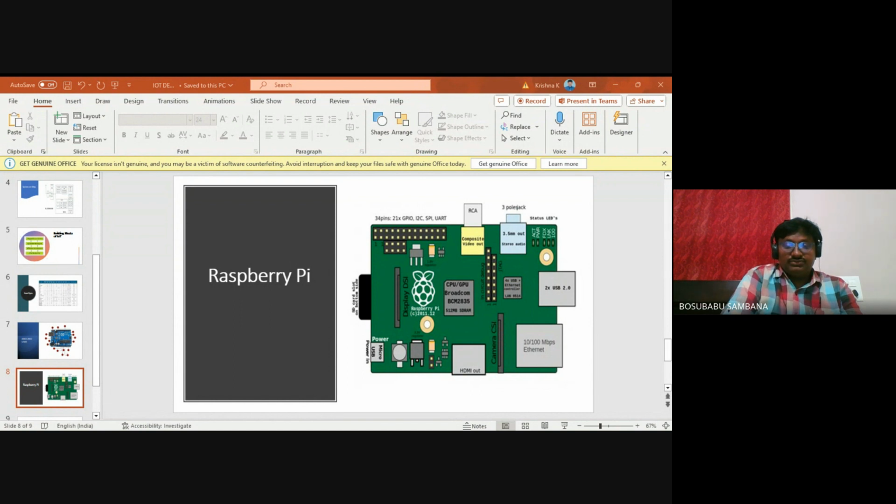Using the Arduino software, you can send a series of commands to the board's microcontroller, allowing you to manage the board's functions. To upload new code onto an Arduino board, you don't need a separate piece of hardware, unlike with older programmable circuit boards. A USB cable can be used instead. In addition, the Arduino IDE employs a tamed version of C++ that facilitates learning. Arduino, with its standardized form factor, simplifies access to microcontrollers.